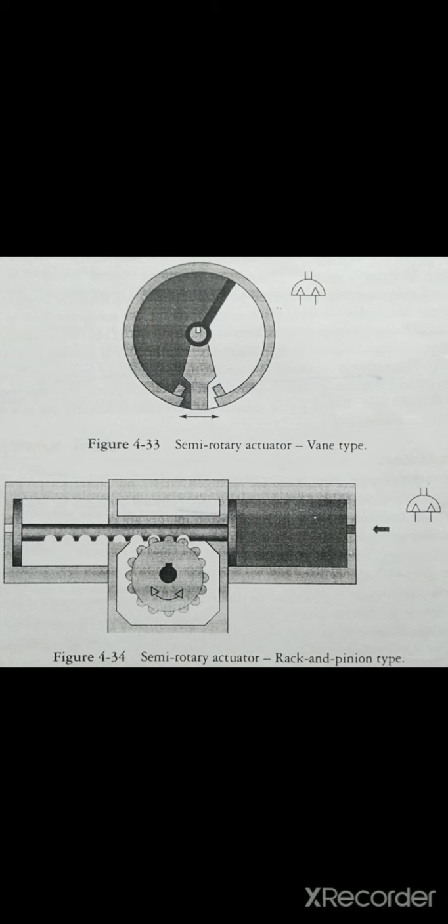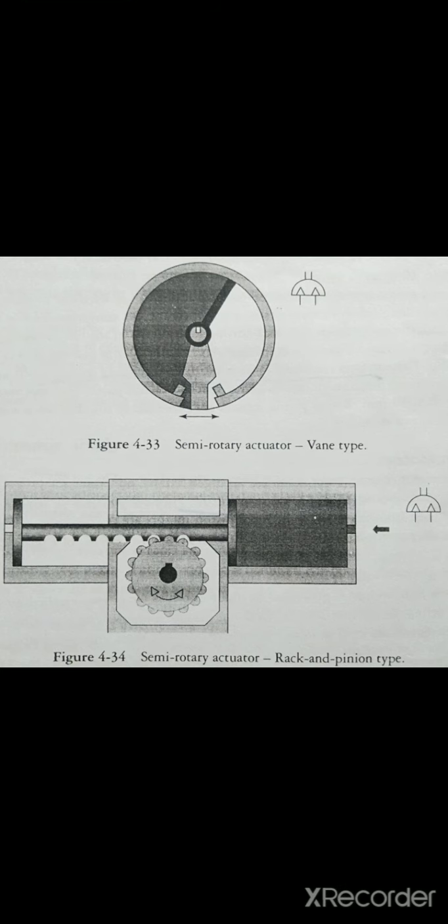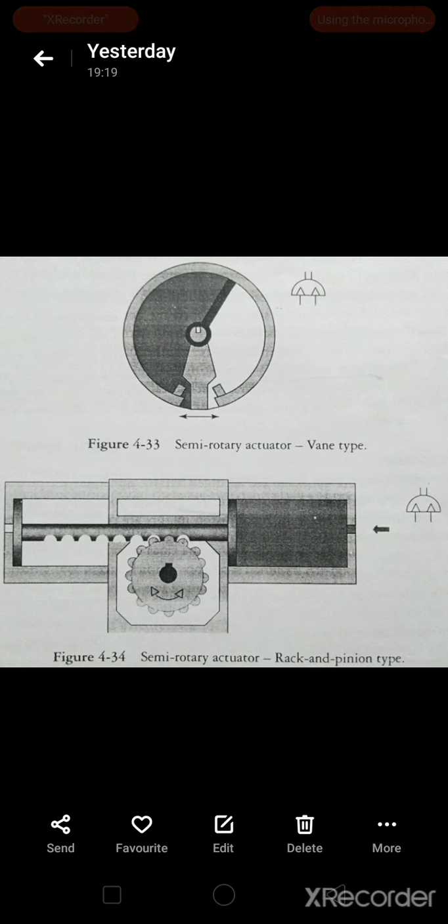the actuator consists of a double acting piston coupled to the output shaft by a rack and pinion arrangement. Angle of rotation up to 360 degrees is possible with this type of design. This type of actuator can also be designed for a double acting, double torque version.